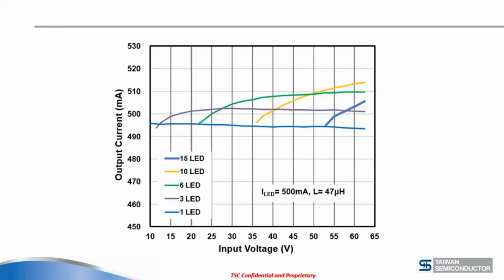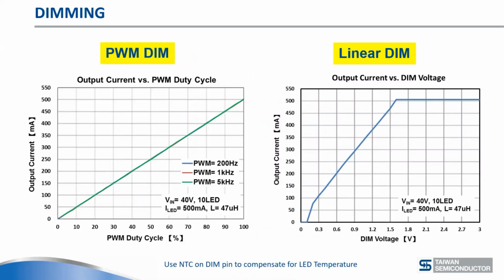And it does work. It depends, of course, on the duty cycles. So the PWM dimming, the 1000 to 1 factor, is there. That works fairly well. I just wanted to show the linear dimming, so you are aware of linear dimming curves also. This is not 100% linear because at 0 volts you actually turn off the device.